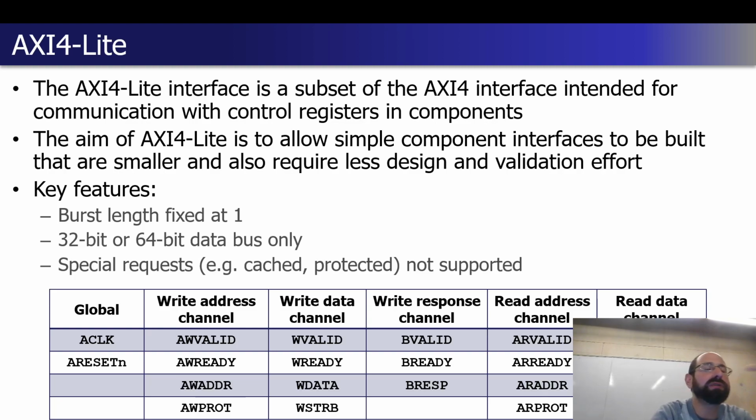That becomes very useful for things like writing to a configuration register on an IP core that you yourself have designed. It's going to be a single 32-bit register. I don't need to send all 256 of anything at a time. I want to either write to a configuration register or read from a status register. AXI Lite is the appropriate interface to do that kind of connection here.